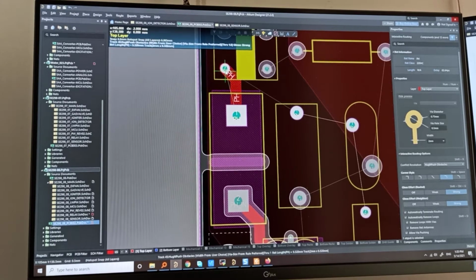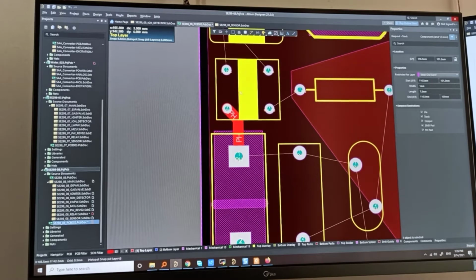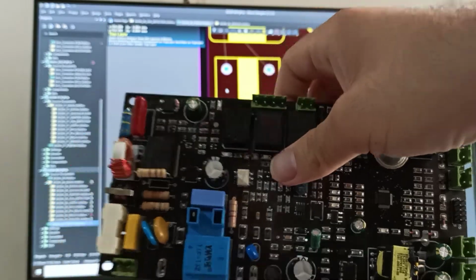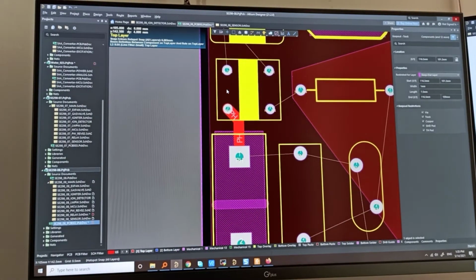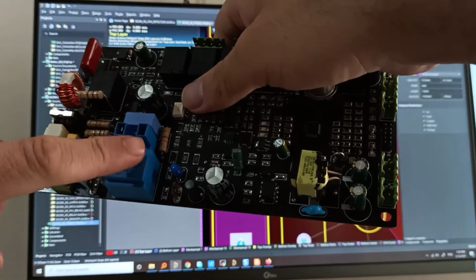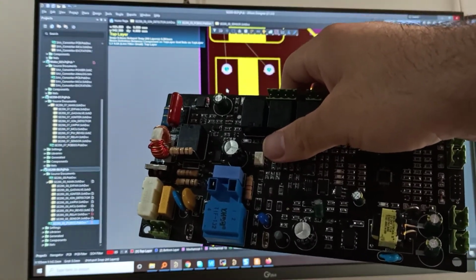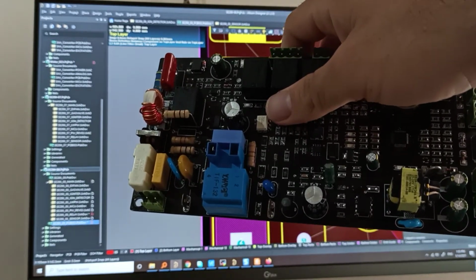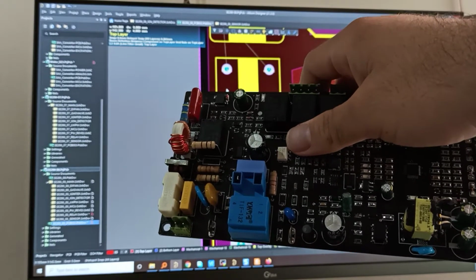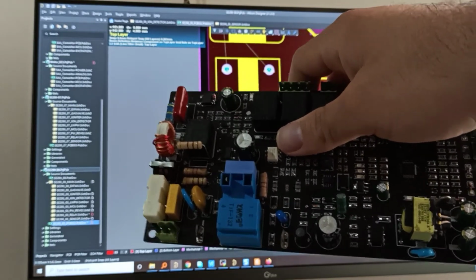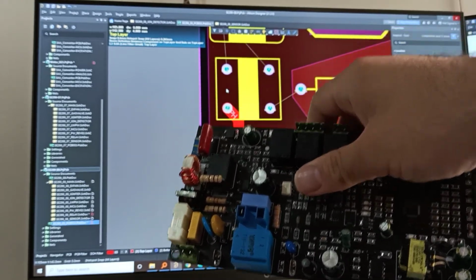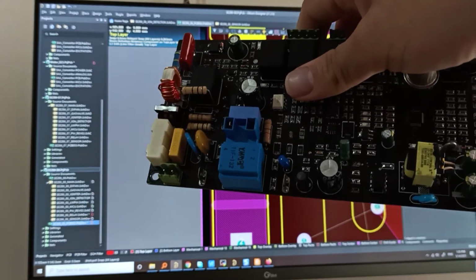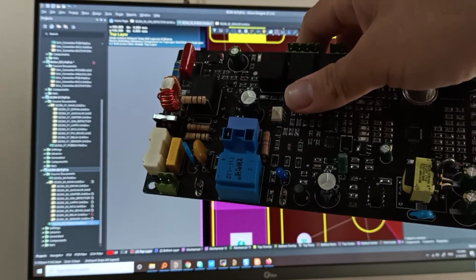Okay, this is the main filter. We can see here a common mode choke. Before the igniter there is 8 kilovolt or 10 kilovolt power. Because of it, I don't use it in the main circuit. I routed it before the filter because I don't want the noise of this circuit to propagate in my circuit.